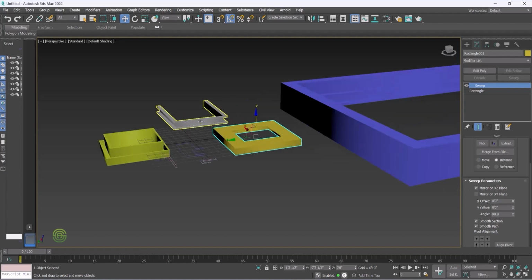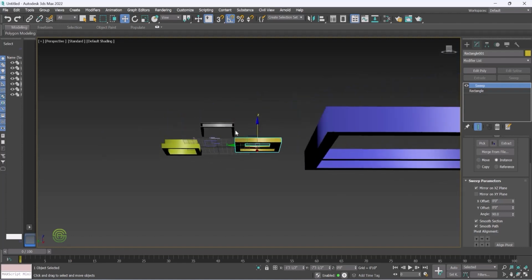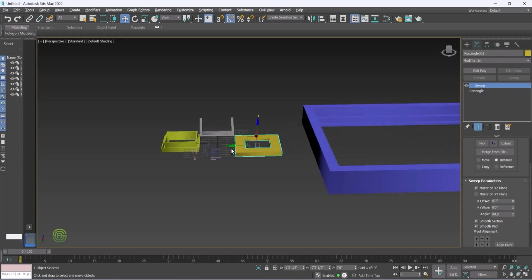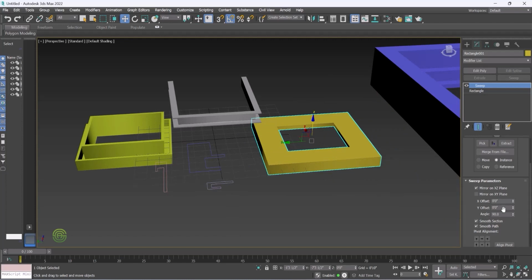In this way, you can use this sweep to create exterior channels or interior cornice or false ceilings like that. In detail, we will learn this further in upcoming classes while we create an interior model. For now, for basic understanding, just see how this works and understand in which way you want it, so that you can mirror it that way, and also angle it however exactly you want it. Once you draw this, you might get it in a reverse order.